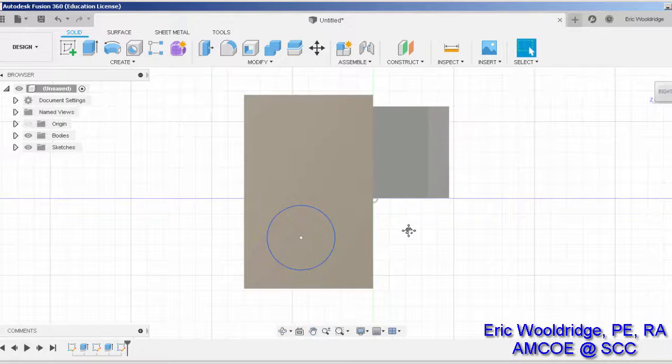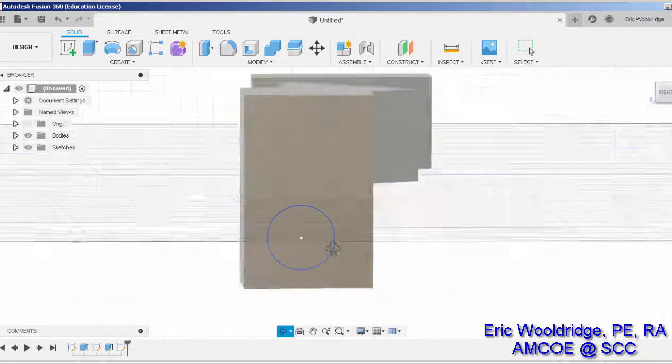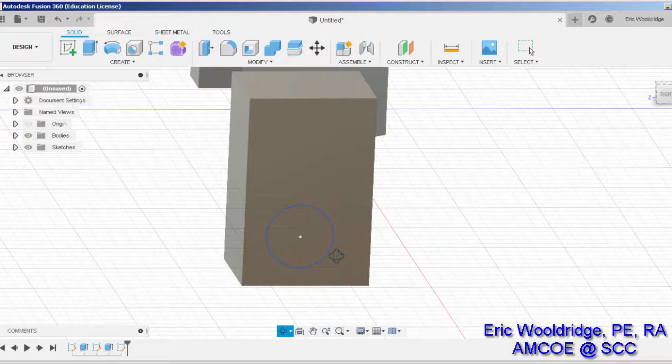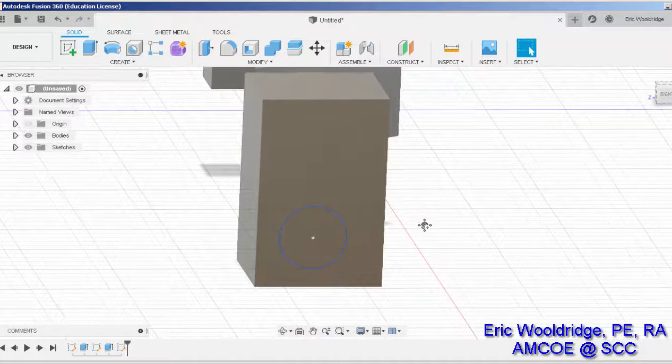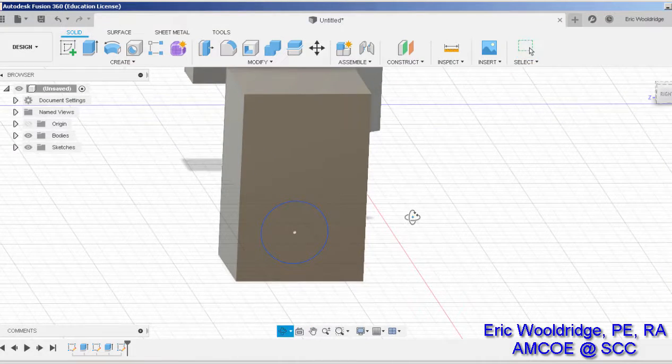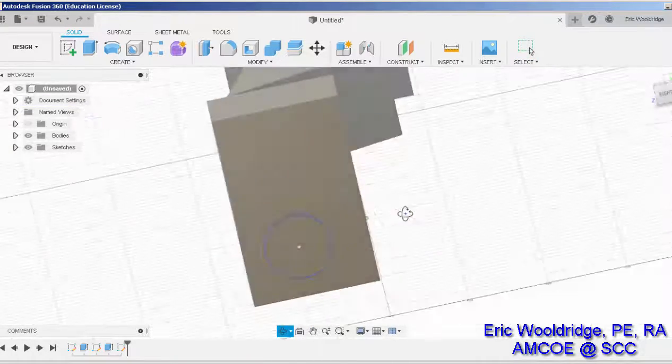And now, to help me understand what I'm looking at, because it doesn't really seem very 3D right now, I wanted to do an orbit. And you can come down and push this button right here to click and drag and get the screen to orbit around, or you can hold down the roller button on your mouse and hold down your control key on your keyboard, your shift key on your keyboard, and you can also orbit in 3D.